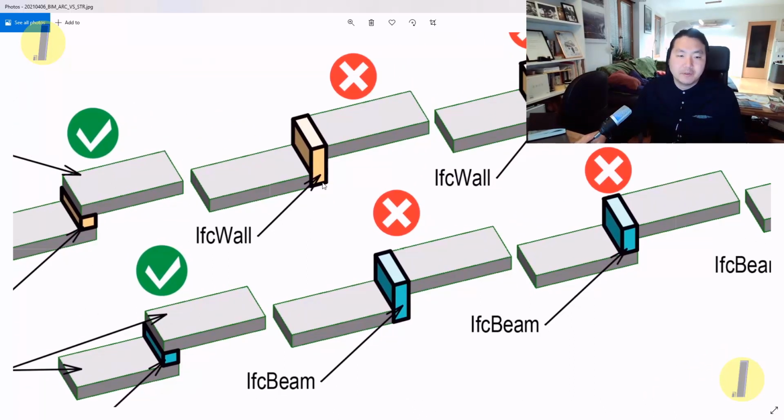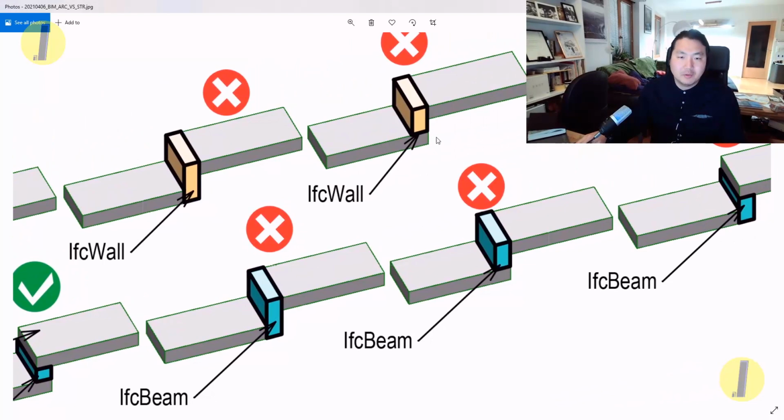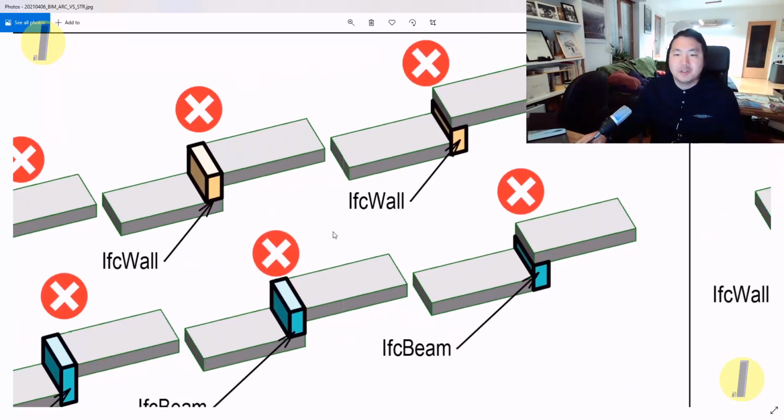But on the right hand side, if you see the geometry, sometimes we get this sort of geometry. So the floor is cut. Basically, this is also correct, because between floor and beam in this case, this area here is kind of the same zone, but this modeling is generally not suggested. And you can have the bottom of the wall above the top of the slab here, but this is also not an accurate model.